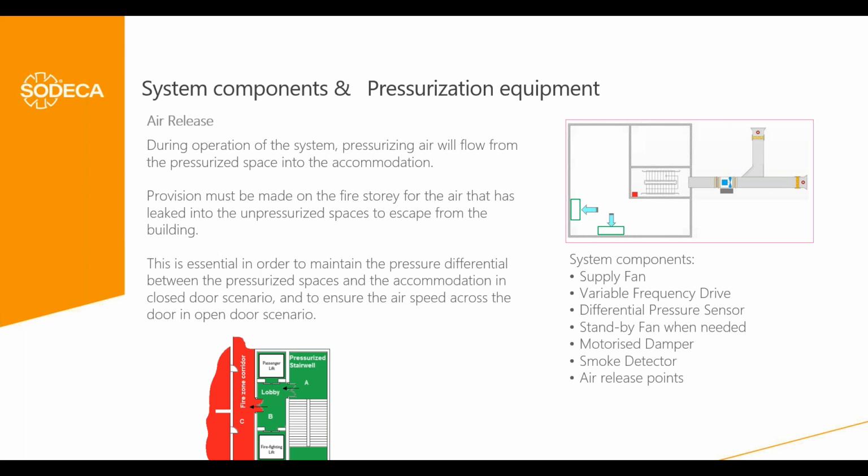The 4th point is one that is many times not considered in the design. For many years it has not been considered. We have been focused in many projects on the pressurization part, but not on the air release. But during operation of the system, the air from the pressurization will flow from the pressurized space to the accommodation, both in the door closed condition and in the door open condition.